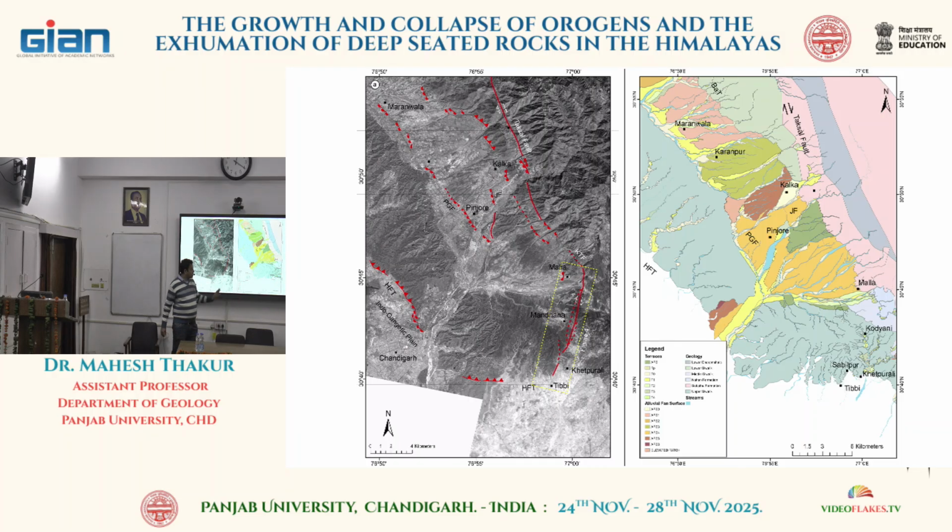In the Cartosat data, you can mark the trace of the fault. You can actually pick the trace of the fault, where the fault is on the ground. These are scarps, some tectonic scarps, so the surface is shifted. Then you can go in the field, take measurements, and try to date the sediments in order to understand when this deformation happened.